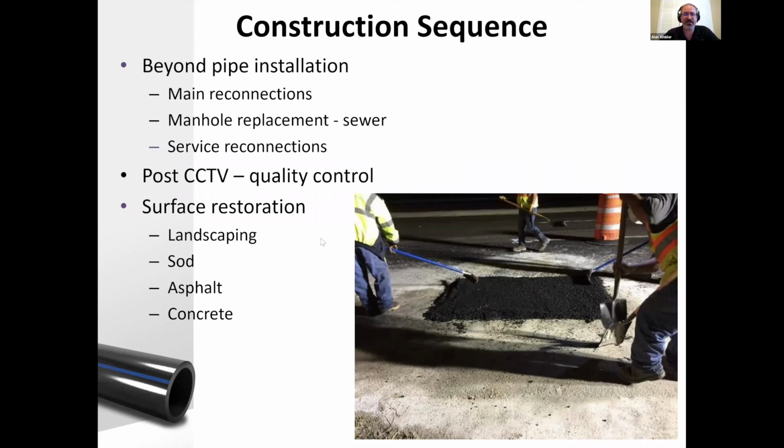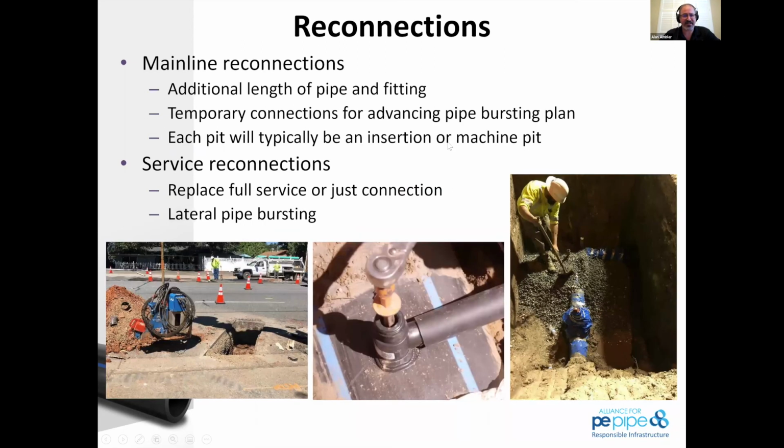When looking at traditional open cut for installation, polyethylene is considered to be a flexible pipeline, and so is PVC and ductile iron. So the same parameters that you would use to install a safe trench are going to be the same parameters that we're looking at for polyethylene itself.